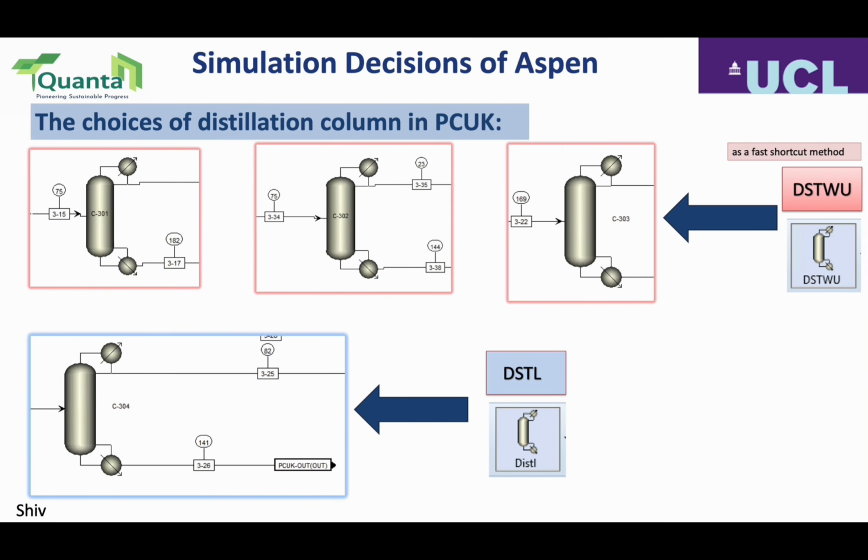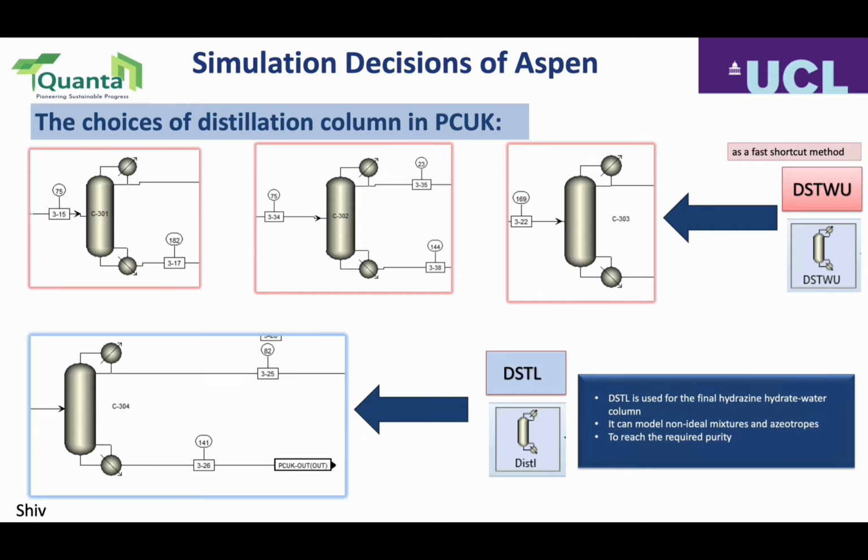Distill was selected to model the final hydrazine hydrate and water separation because it performs full equilibrium calculations and can handle mixtures that do not behave ideally, including azeotropes. This allowed the model to achieve a realistic representation of the limited separation possible between the hydrazine and water.